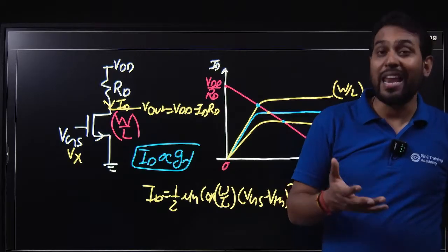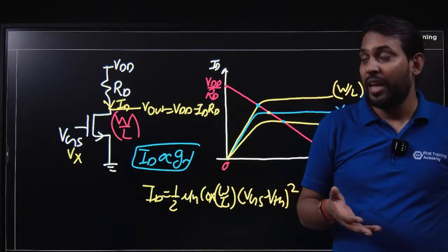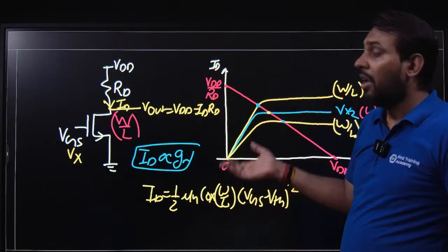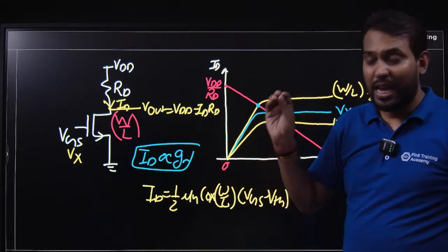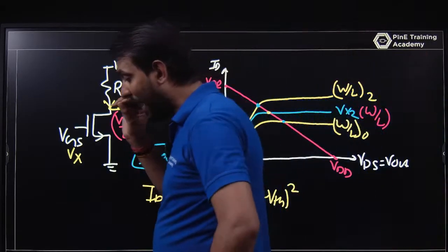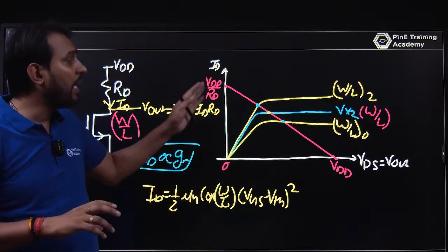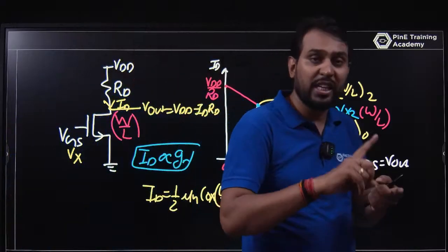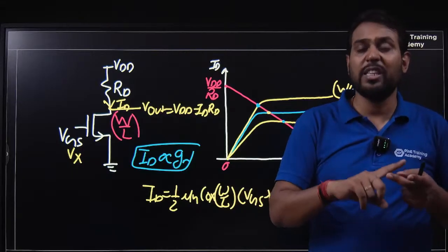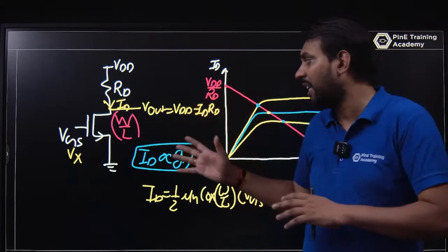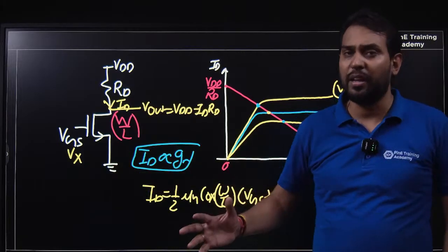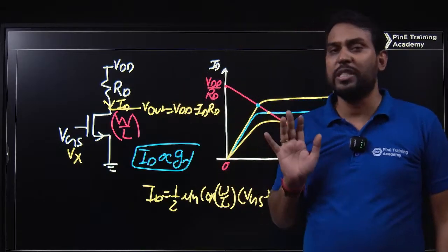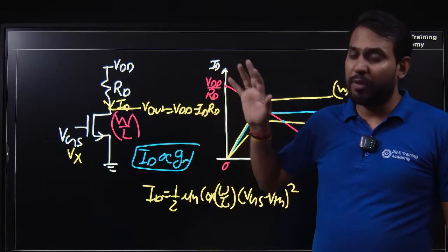Okay, you can do the DC analysis. Here I am just explaining ID versus VDS or ID versus VGS. You can give that command to Cadence, and it will provide every plot: ID versus VGS, Gm versus VGS, and CGS versus VGS. Every parameter, as you have in DC. In DC, the MOSFET has a lot of parameters. But if you say, okay, I want everything with respect to VGS, it will provide everything in terms of plots.